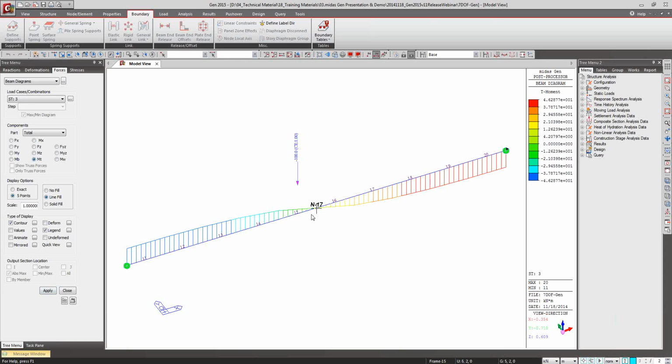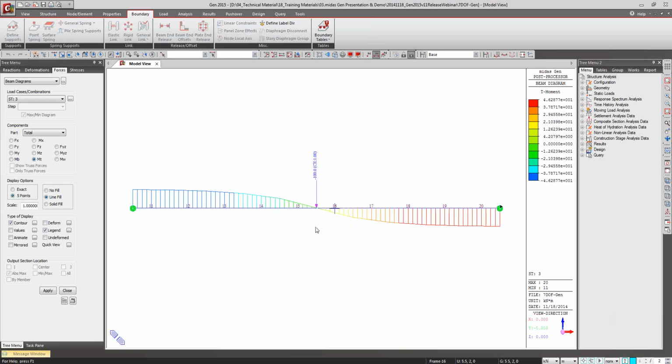Firstly, the Saint-Venant torsion, the uniform torsion, occurs largest at both ends, and it is 0 at the center with this eccentric loading applied. And for the warping torsion, we did not restrain the warping at both ends, as I mentioned. So when warping is not restrained, in that case, there will be no warping moment.